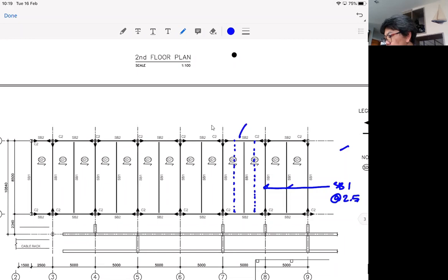This time you will put whatever load you have assigned on your system from the first phase onto this, plus the weight of the slab. What comes before is what you can call the superimposed load, right? Any load that your slab has to carry, plus the weight of the slab.